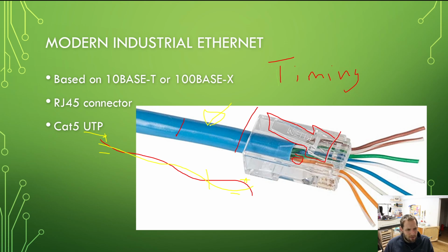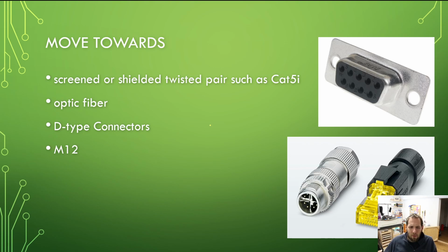In industrial environments, again, we've got lots of moving parts. We've got dust, we've got heat, we've got all sorts of things. So that cable may be flexing a lot, or maybe getting stepped on or hit by accident, so that cable could slowly be getting worn over time. So that's another thing you just need to keep in the back of your mind. But anyway, the outside of these industrial Ethernet cables is going to be a different material. Traditionally, it's going to be a flexible polyurethane, so that it has the longest performance life in harsh industrial environments.